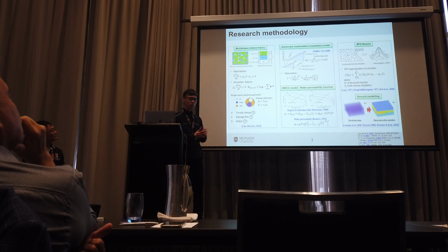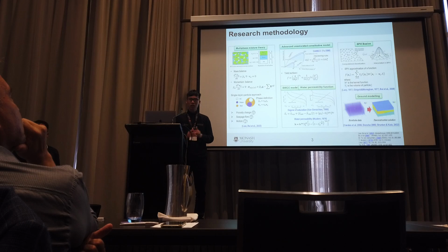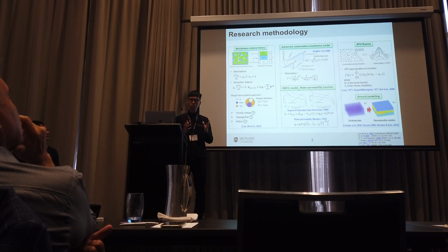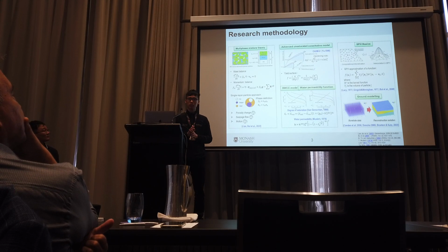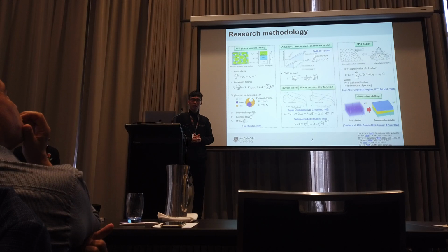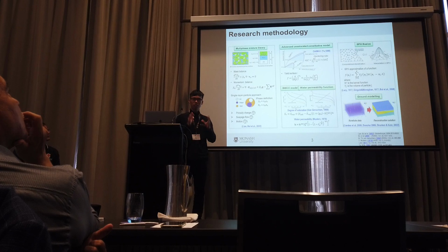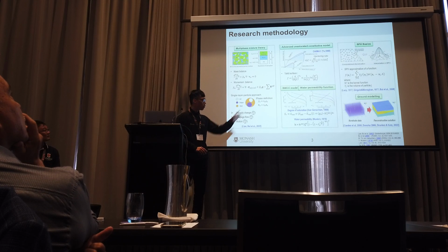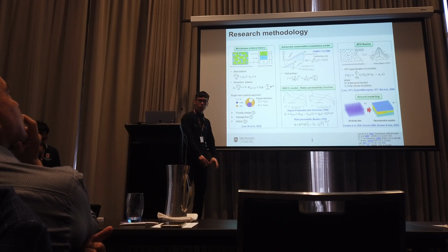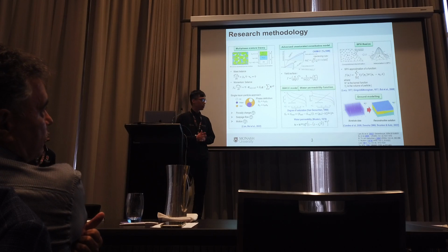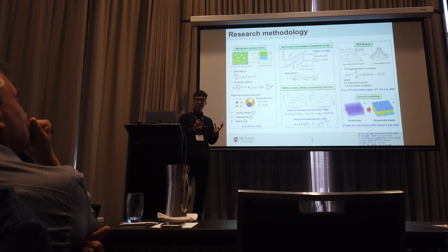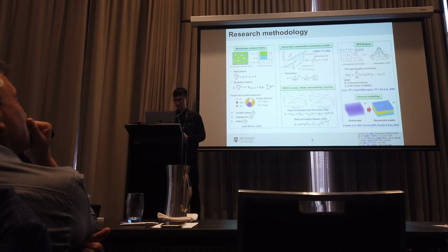And finally, to solve the governing equation, we need to use a numerical method for solving the spatial derivative. Here we're using the SPH method. So the SPH is the continuum mesh-free method, in which particles carry field variables and move with the material velocity. After we complete the framework, when we bring it to reality, we often see limited data. So that's why we also developed the ground modeling. Basically, if we have some borehole data input, we use optimization to reconstruct the entire soil profile, and then do the simulation.